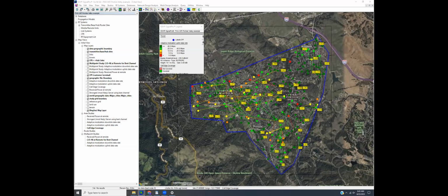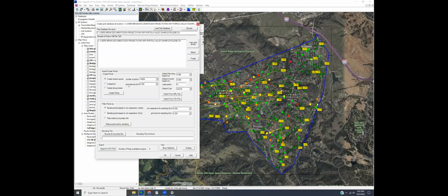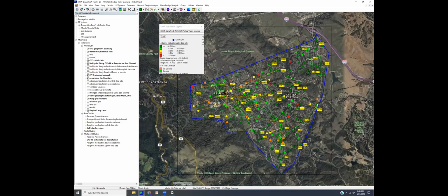Yeah, it does. The difference there a lot of times is that you may not have a list of the candidate locations when you're in a building. Sometimes folks do, and that's fine. We can work with that. But usually, if you're already familiar with the outdoor auto placement for areas, the extra step that we would do in a DAS indoor project is just to go under towers and poles and use that create grid of points to dummy up a bunch of candidate points on the floor that you could use if you don't know exactly where those candidate locations are going to be.